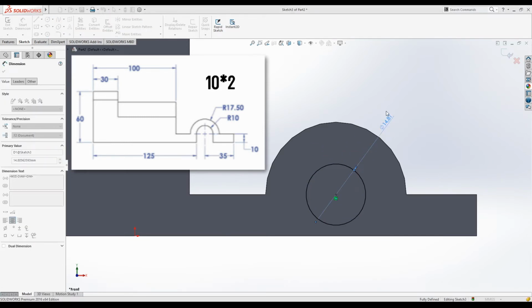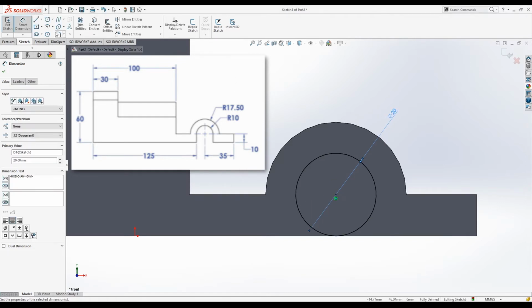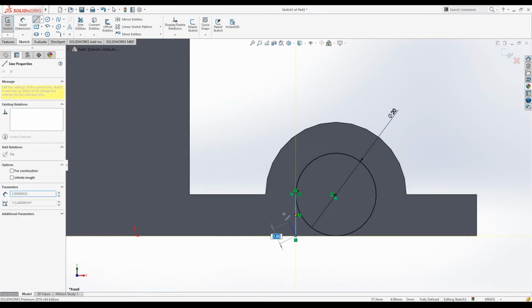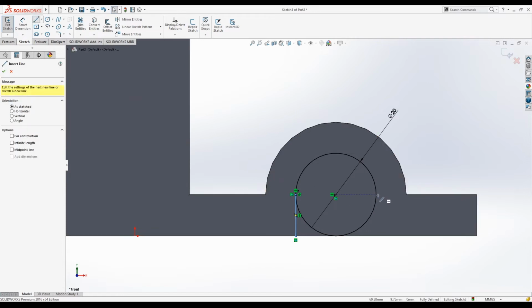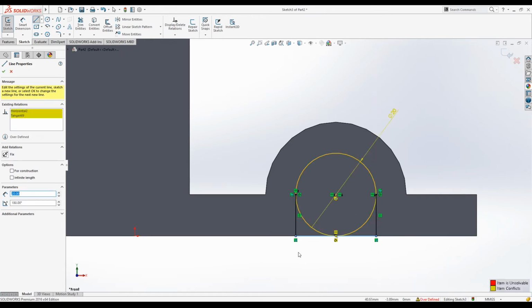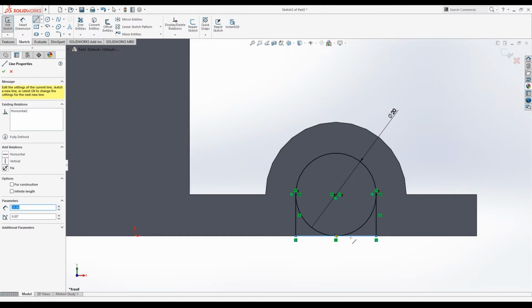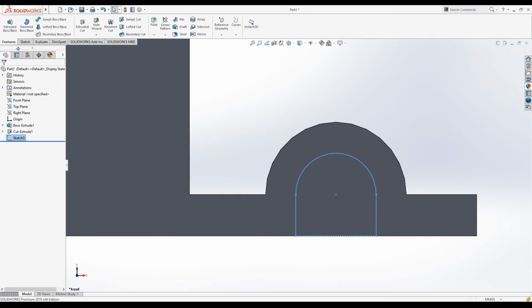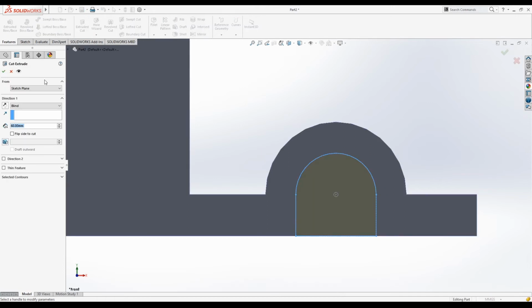Like so, click OK. Next, select Line and make 2 lines from both sides of the circle down below the edge. Put another line, horizontal line, on the lower edge connecting the ends of the lines from both sides. Trim the lower parts of the circle. Select Sketch and then Extrude Cut 2. Select Through All in End Condition, then click OK after.